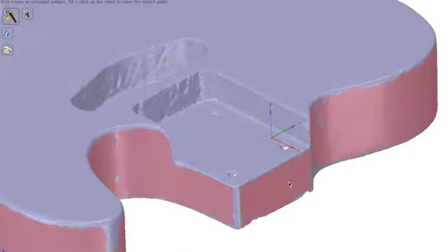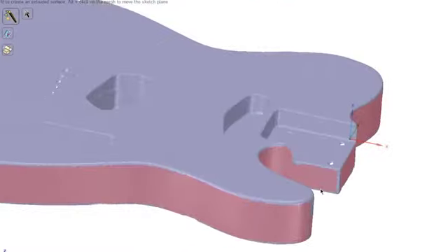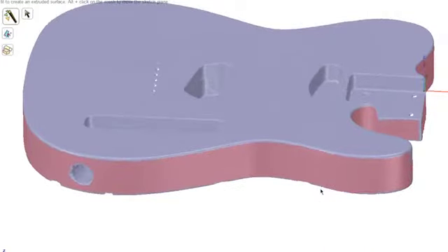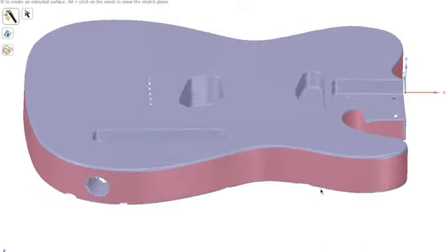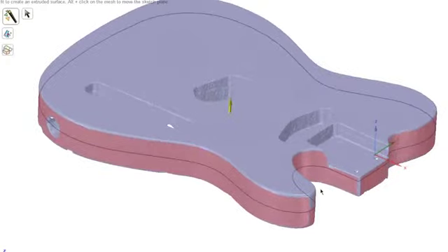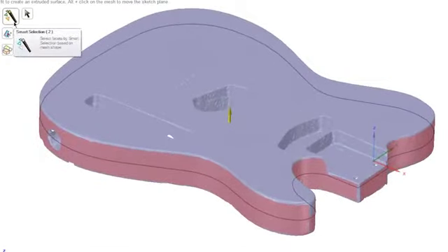So you can see I can make sure that I have a complete selected area around the outside of the part. And it's very easy to click and select triangles in here because we have a smart selection tool which allows you to click and drag and gesture on screen up and down, and it'll select more and less triangles and fill that entire region and help you select very fast.